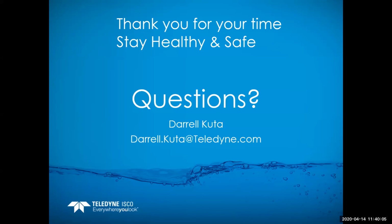Let's see, another question. Which technology works best for gravity flow sewer pipes, meters installed in manholes? As far as gravity flow, I would use one of the velocity sensors we talked about, either the continuous wave Doppler or pulse Doppler or the non-contact velocity sensors, because they're going to be able to read the depth to calculate the area, and they're going to be able to read the velocity. So we aren't concerned about the slope or the roughness. And like I said, they'll read the velocity and give you accurate flow readings.